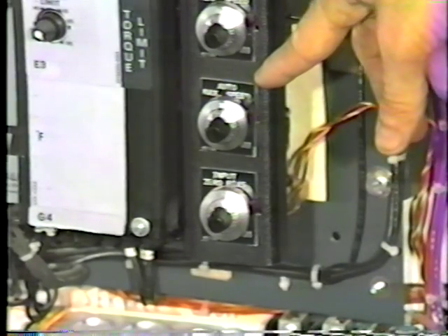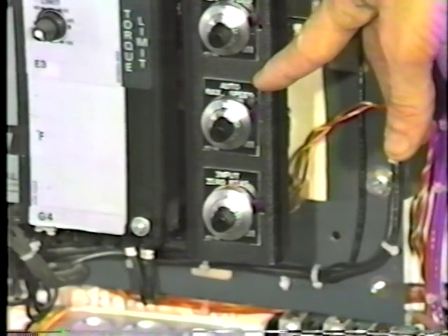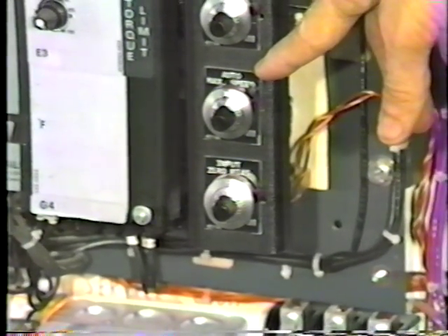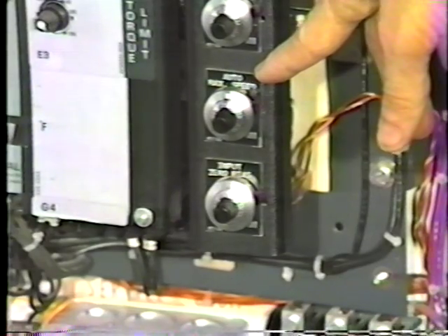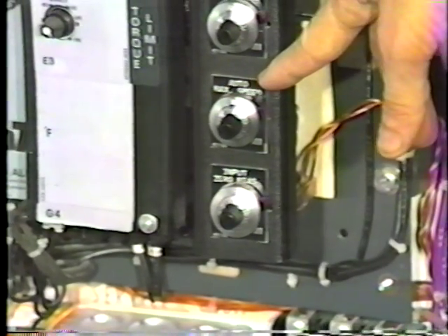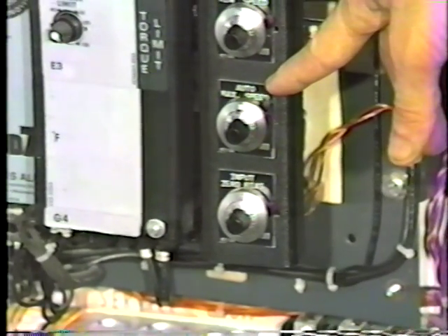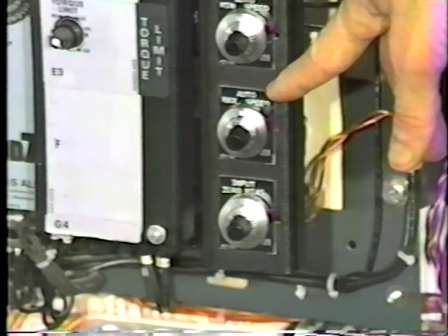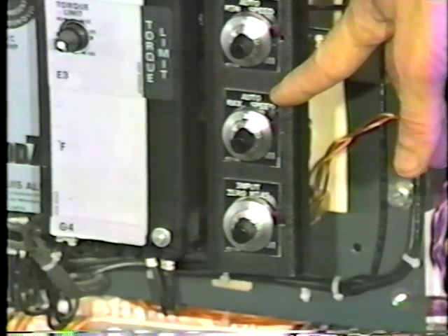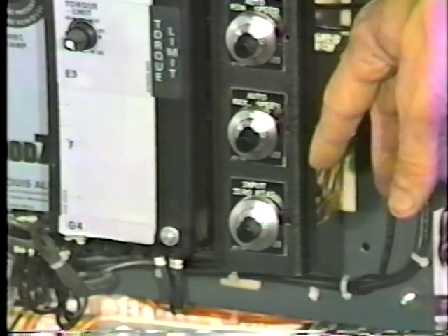Next one is our automatic maximum speed. Okay, so that can be set for any value that we want to limit the upper range of the mill in automatic. Correct. So that a 20 milliamp signal from the boiler will represent the maximum output that Foster Wheeler wishes for that particular set of burners. Correct. Okay, that will be adjusted. Correct. All right, the next one.